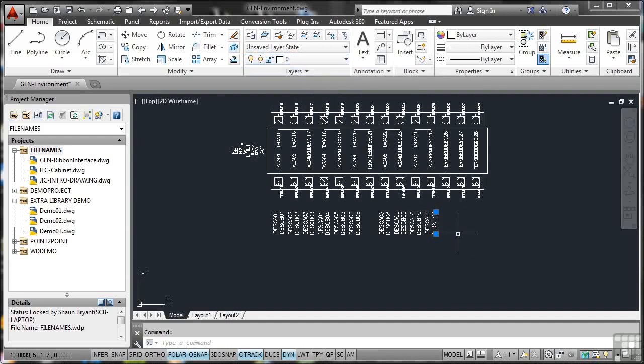What you should always do is create all of your information to make into a block and put it onto layer 0. I'll just hit escape there and just hover over that again like so. And as you can see, it doesn't highlight any name or anything. That's because it's an attribute. All of those attributes have a meaning or a definition.